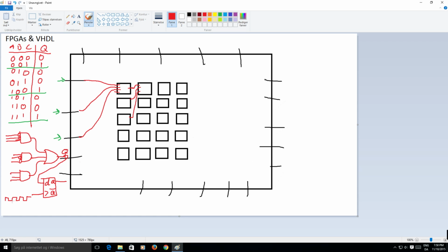And then whenever we have a rising edge on the clock, it would take whatever is on the D pin and put that on the Q pin, and the opposite on the Q naught. So this way we can reference everything to a clock signal, and by cascading the flip-flops in series, we can make counters and stuff like that. And by putting them in, like parallel, we can make registers.